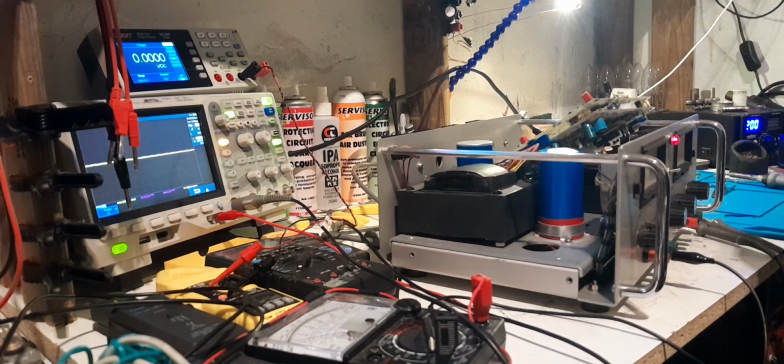The last transistor's gain is like 400 or something. So although the last two in the chain are low gain, I think the one before it and the one before that are making up for that. You know, it's basically a triple Darlington. So I don't think the op amps aren't sourcing enough current, but it also is a possibility.